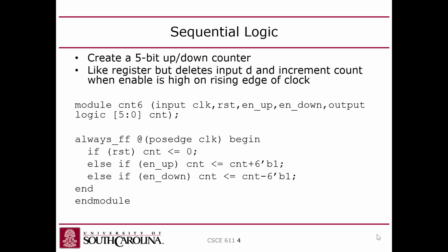But in Lab 1, you designed a shift register that shifted 1 bit per cycle. So in that case, the state was the value being driven to the LEDs, so the location of that single lit LED.